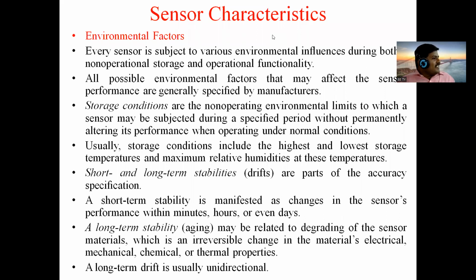We check the insulation, right? So any machine that has been stopped for a long time, if we want to put that machine into operating condition, then first of all we want to check the insulation between winding to winding. That means we are conducting a Megger test. Without conducting a Megger test, we are not directly putting that machine into operation. So like that, there is some specific time period or limit within which we want to operate that equipment, like a sensor.